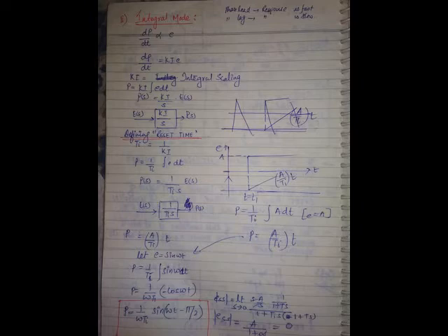Before the error has occurred, this controller is sending a signal to the control element. Before the level is rising, it is about to change, it has not even started changing. Suddenly it is opening the tap. The water level is still at the set point, error is 0, but the controller is sending a sudden signal to the control element. Suddenly it is opening the tap. What happens to the water level? It will fall.